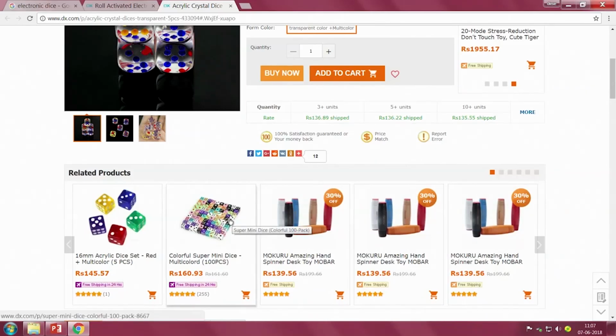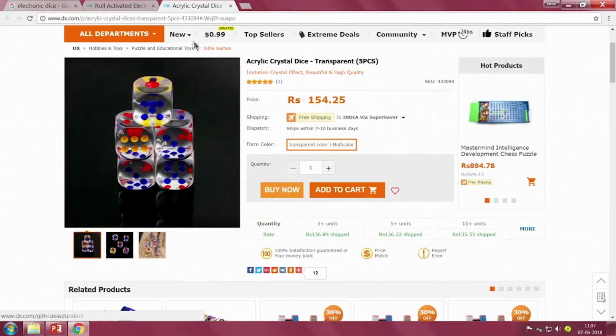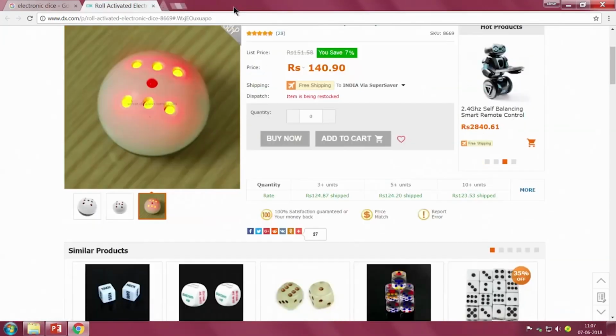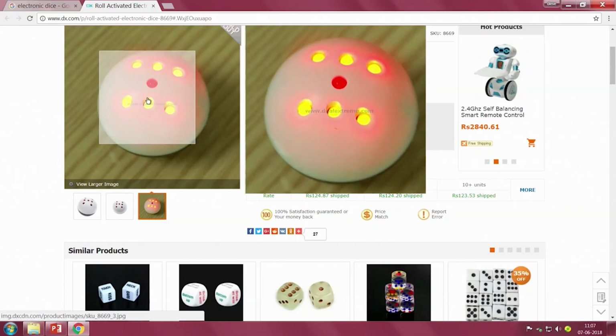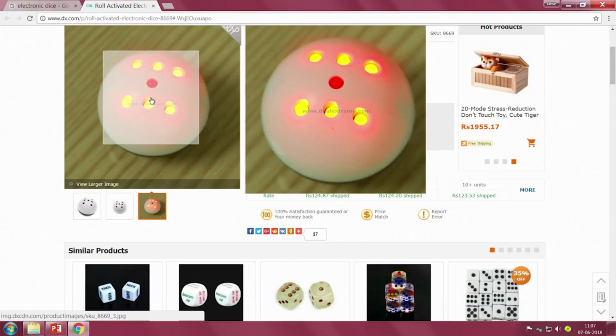So, I am very happy to have helped you in looking up a few things here, and see here, this to me is something which you can very easily print in rapid prototyping. Why rapid prototyping and why printing? The outside object being spherical, sanding it is easy, you understand, no. Take a sandpaper, and in fact wet sanding, if you have, you can start with probably 80 or 100 and then finish it up with 300 or 400, and if the material is good, naturally it stays good.